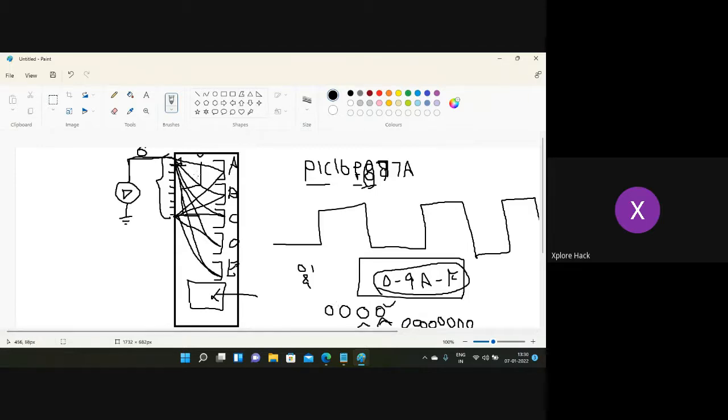If you take the microcontroller, we have only 8 different input and output pins, so it is enough if you use these 2 digits of this hexadecimal number. That's why we placed x before these 2 digits, because the machine does not need to worry about the other digits of this hexadecimal value. Totally we have 8 different digits within this one, so it is enough to access 8 different pins.